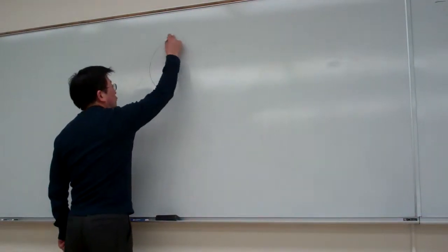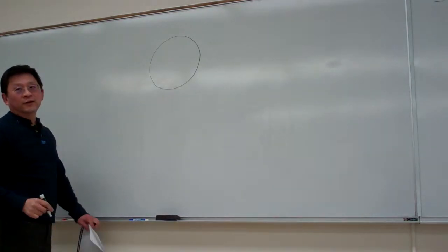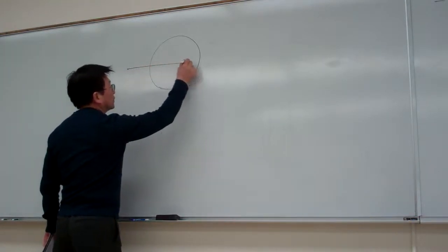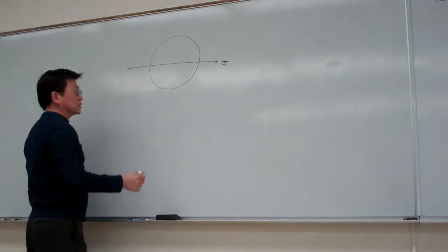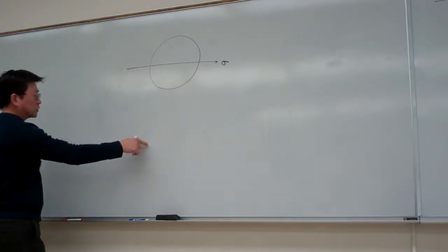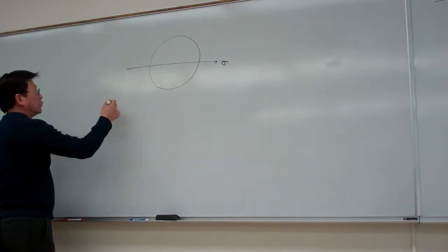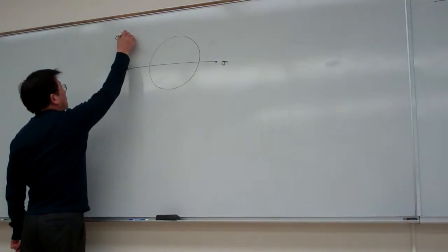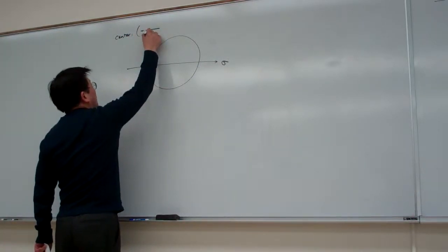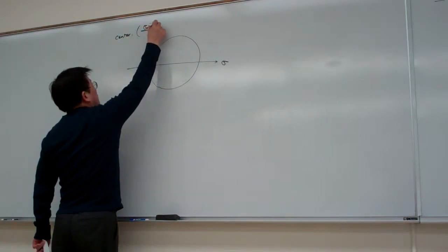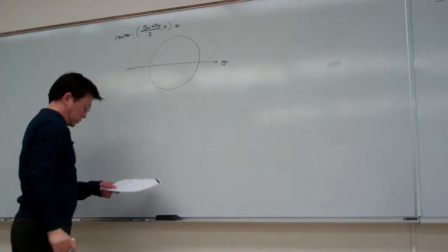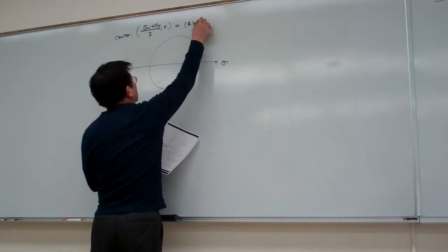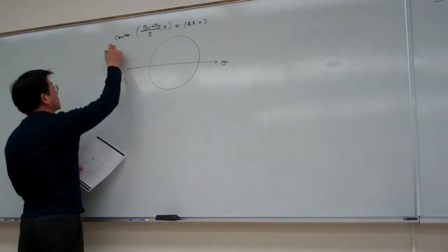So if you remember the Mohr circle, basically that is really a circle. To determine the location of the circle in the normal stress and shearing stress plane, we need to determine the center. The center of the Mohr circle is at the average of the normal stress and 0. Okay, so for this case, the average is at 4.5 and 0.